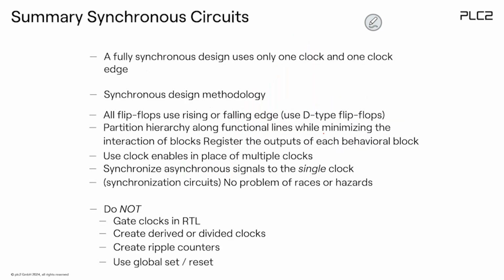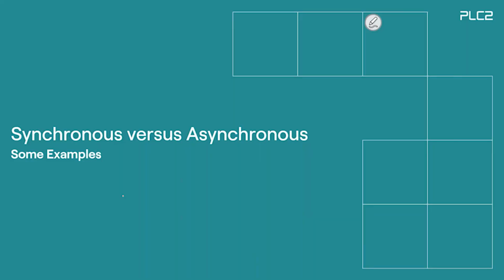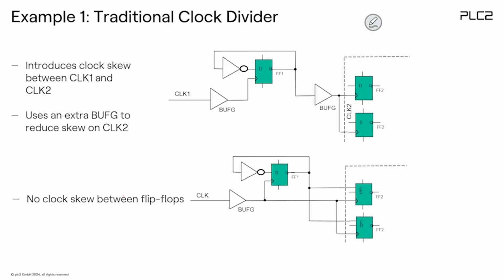Okay. So this means just again a summary. That's what you already know. Use just one clock, and do not do something like this. Use a buffer, the special clock buffer, in order to implement this function. Some examples.